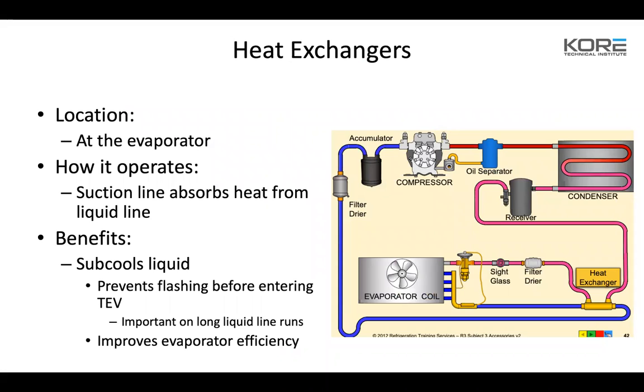As you can see in this graphic right here on your oil separator, you see that oil flow. Anytime you're dealing with a separator, you're going to deal with an oil flow. What the flow does is determine how much oil will be allowed into the compressor at any given time. So when there is an adjustment on this flow, what I would suggest is we don't make a habit of adjusting those. They very rarely need adjustment, and most of the time when we adjust them, we end up changing them. So usually once you set it, they work or they don't.